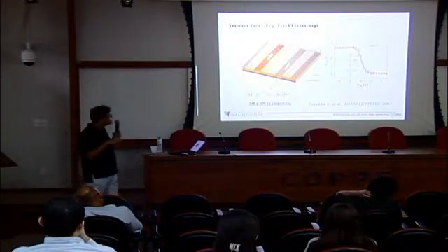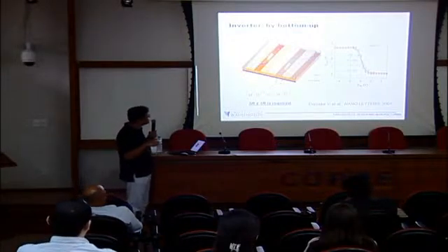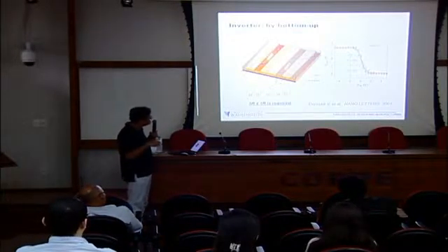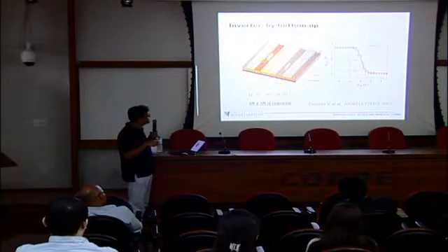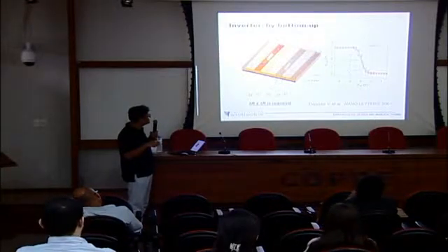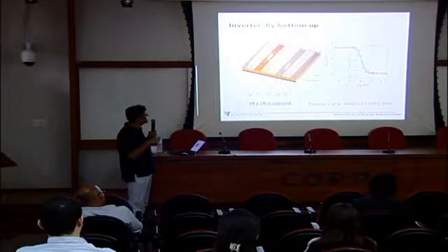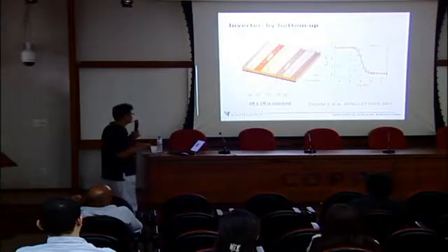And if you see the voltage characteristics, then it's much better than the silicon nanowire. If you apply 2 volts, then the output is -2. Okay, and then if we apply -2, then it goes to 1. So we can make it reversed. It means it's an inverter.